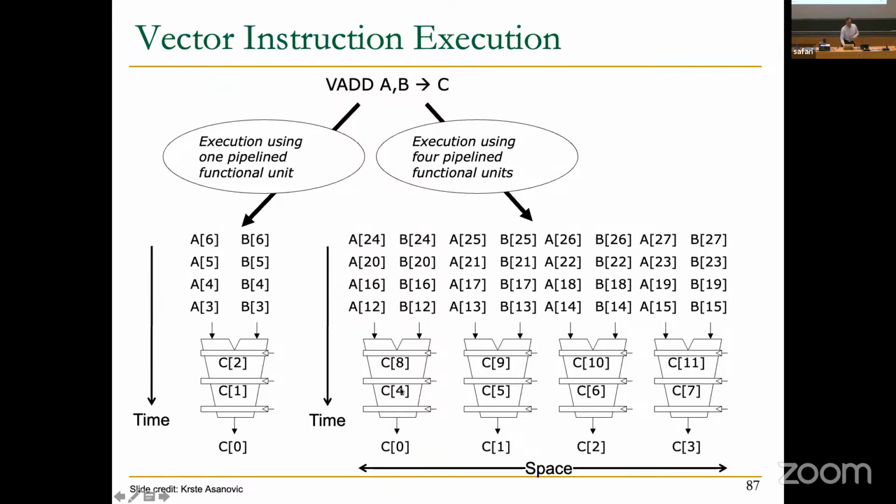That sounds good. Now you can also customize the register file. Elements that are numbered 0, 4, 8, 12, 16, 20, 24 go to this one. The other ones go here. Basically, there's a function, a mapping, a partitioning of the register file across these functional units now. Not all registers need to feed all functional units. This makes it a little bit harder to program, actually, later.